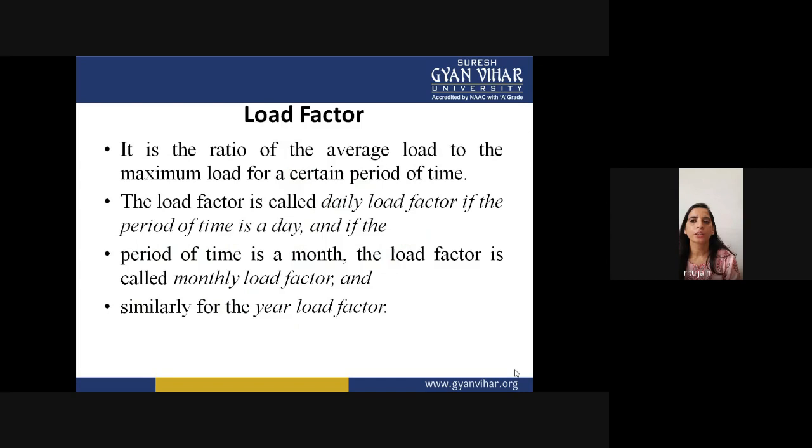The load factor is called daily load factor if the period of time is a day, and if the period of time is a month, then this is called your monthly load factor. Similarly, if the period of time is a year, then this is called your yearly load factor. Because your average load is calculated on a daily basis, monthly basis, and yearly basis, right?